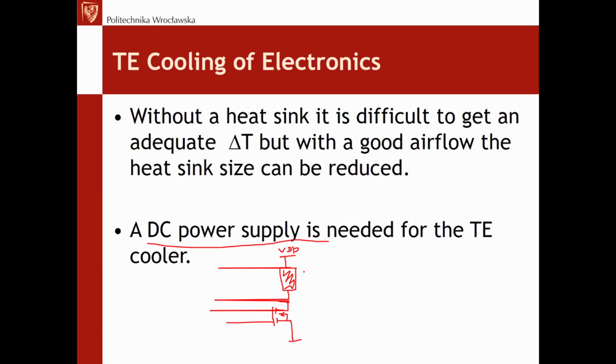But of course, this very simple circuit has one serious disadvantage: it's just either heating or cooling, because it's not changing the polarization. Here we are just keeping the same polarization. The second problem of this circuit is that it's about full power or no power. It's switching on 100% cooling or 100% heating, full power, and then power off completely. So that's the disadvantage of the circuit.